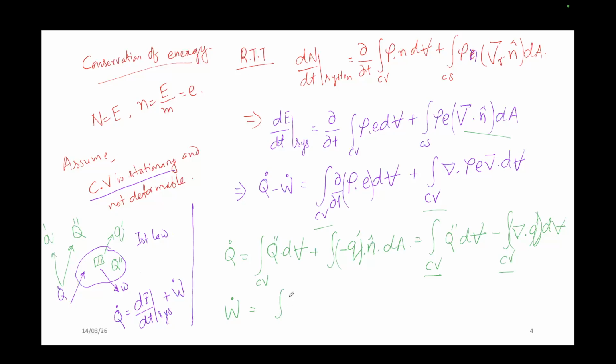So this shear term, if I talk about, this is tau ui into the area I need to take, into n cap. This is a control surface property, so it should be in CS, and the control volume term is there, which is your body force. So this is Bi into. Accordingly, we have to convert control surface into control volume. So I will get this term.